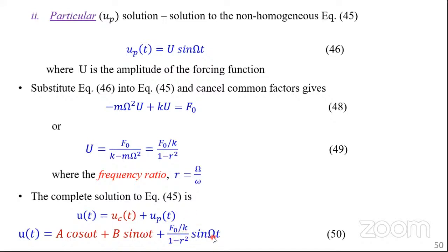Now we have the frequency of the forcing function. If you look carefully here, the second part, the particular solution, is the one that contains the aspect of the forcing function. But the complementary solution is kind of a free vibration motion, and you're going to see what this means for our equation. But this now is our response. This is our complete solution.